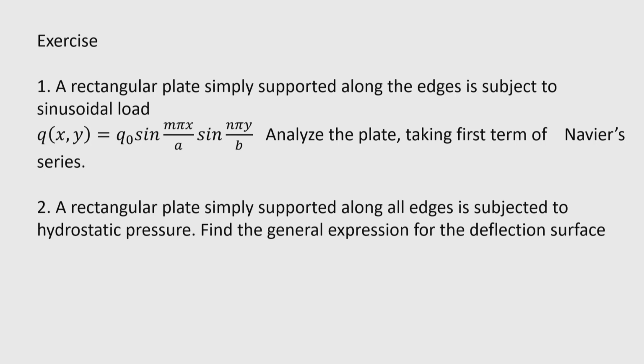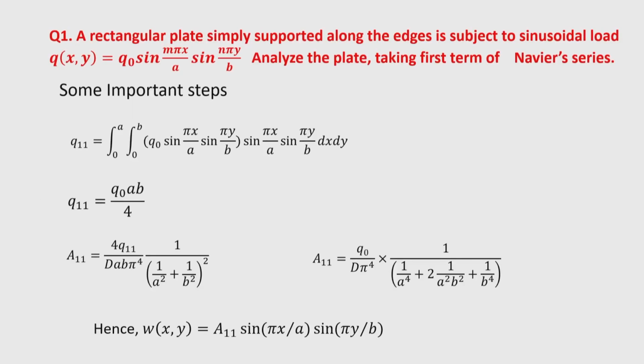So, the first problem will be solved like that, and for the second problem we have taken a rectangular plate simply supported along the edges and subjected to hydrostatic pressure. Find the general expression for the deflected surface. These two problems can be solved by Navier's method. That is why I have selected them. For the first problem, I am giving some important steps.